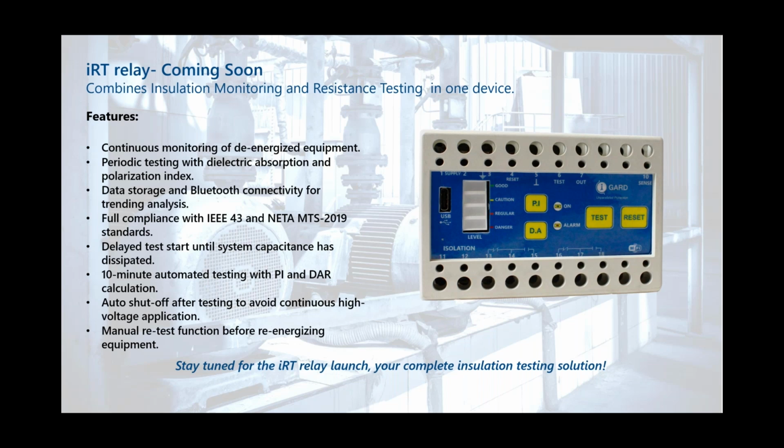There's an auto shutoff after testing to avoid continuous high voltage application, and a manual retest function before re-energizing the equipment so that you can confirm that the motor would be available to come online after that test is completed and the values are within range of a good insulation resistance reading. So stay tuned for the IRT relay launch, your complete insulation testing solution. This model will go between 600 volts to 13.8 kV, and it would give you indication as seen here on whether your insulation is good, there's a caution, if it's regular, or if it's in danger.